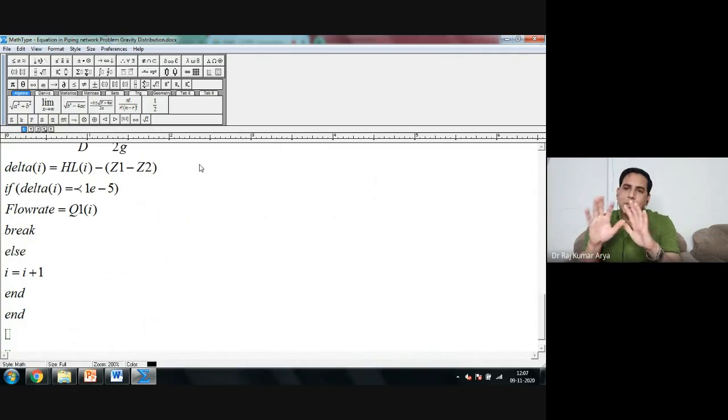So this way you would always calculate the flow rate when you design a gravity flow or any pipeline where you know the elevations and all this. Or let's say somebody has said this is the maximum pressure drop, this is the diameter of the pipeline, now you tell me what to do. How much would be the flow rate? Because there you have two unknowns. One is flow rate, one is your friction factor. You cannot fix either of them, so you have to fix them where they will fix themselves. Is it clear to all of you?